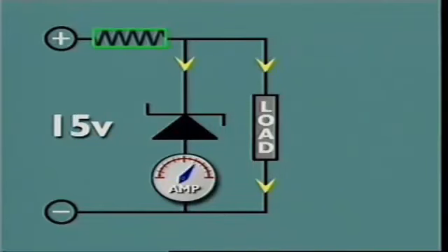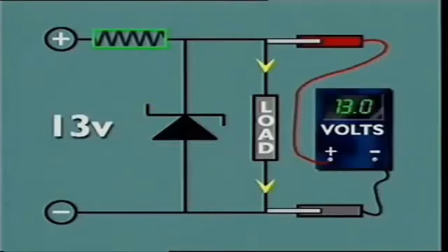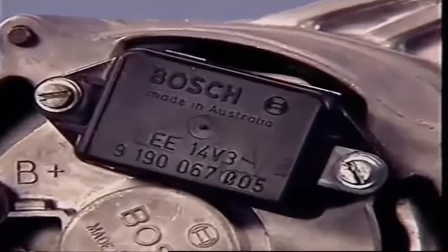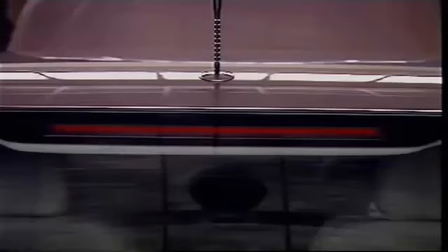This is called breakdown. A Zener diode is designed to operate in this way. As breakdown voltage is reached, the Zener diode's resistance suddenly collapses. It lets a large current flow through it without damage. Because Zener diodes respond to certain voltage changes like switches, they are used in voltage regulators. Light-emitting diodes, or LEDs, emit light when they are connected in a forward direction.